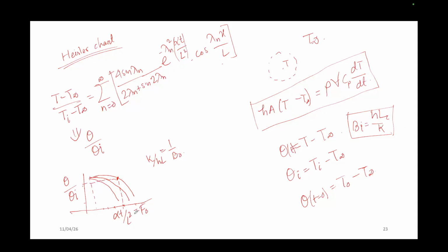So this is one curve with respect to your Fourier number. Next, another curve is there where this one is theta by theta 0 or theta infinity, theta I. This one is the same, initial or 0, whatever you want, you can write. This is not an issue. This is k by HL, so here it is the slope. Now here k by HL comes. Now the thing is that in those cases you will observe the curve should be something like this one.